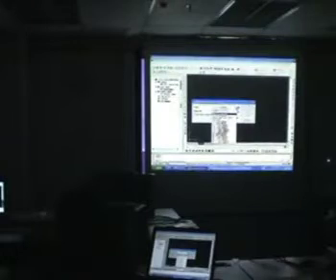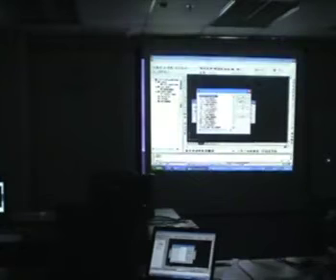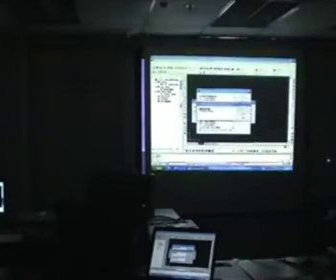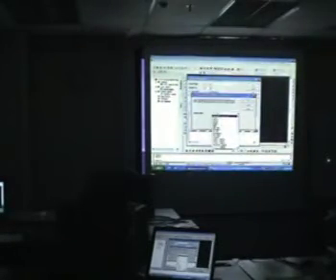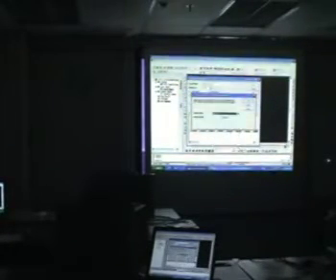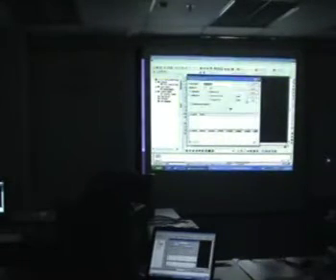In the event that you have a file whose format is not listed in here, you can also make your own format. For example, let's say your company uses MOS, and MOS does have a lot of text formats as well. So let's say we need to import that and you find the format is not listed in this list here. You can make your own format. Just click on the icon on the right side here, click add, use a point file, and this is where you can create your own format. For example, maybe the first column is something very unusual, maybe longitude, or maybe latitude. So it's very free in a sense. You can make your own format.